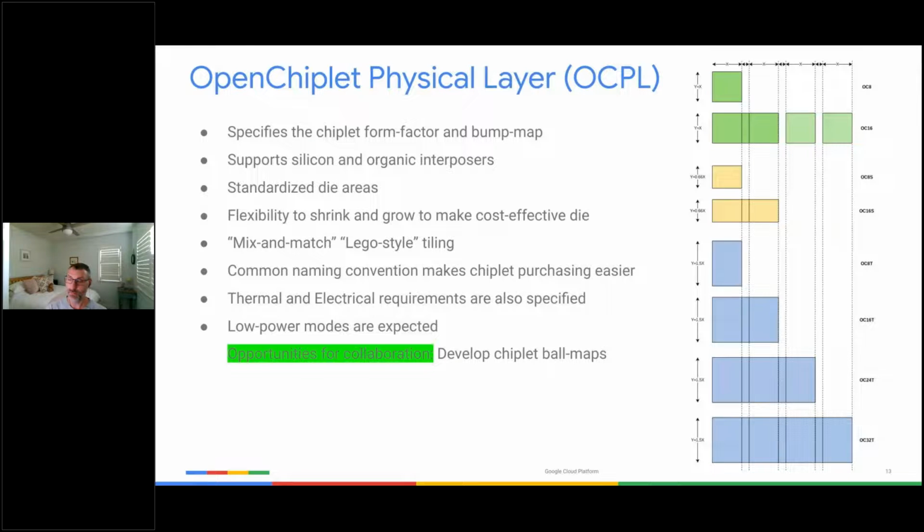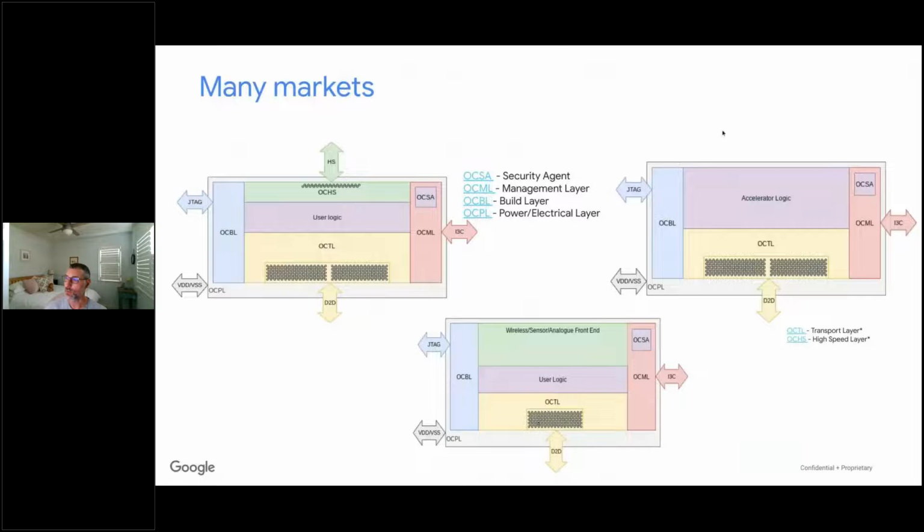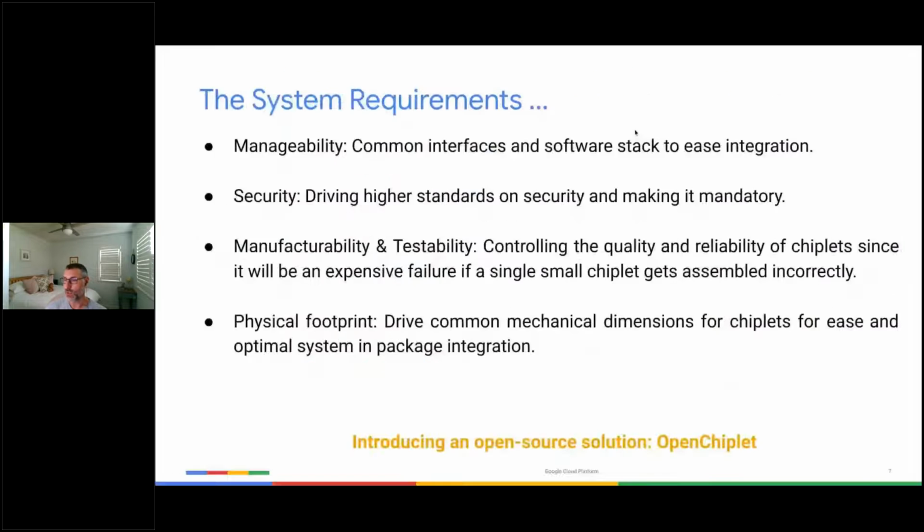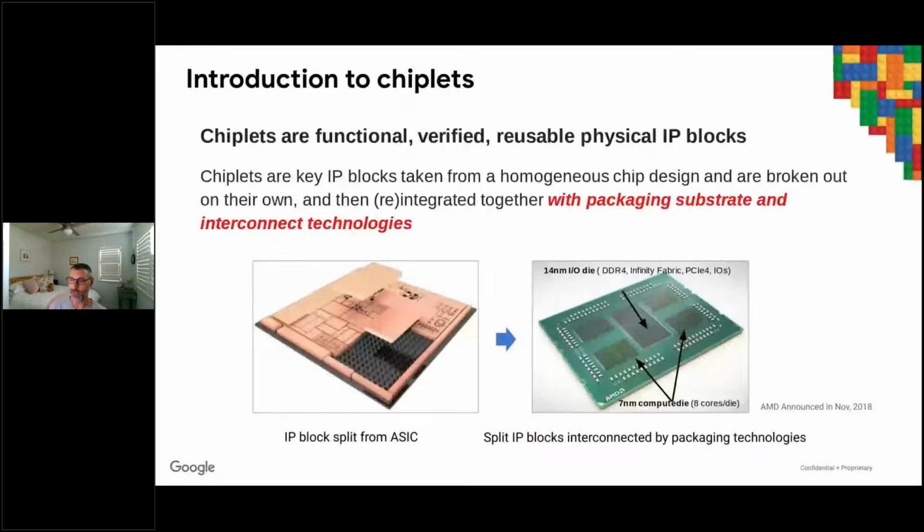Yeah, because if you went to a picture that looked like this orange thing, you're tessellating and tiling dies all over the place. It's an awfully complicated thing to assemble in the first place, just matching all of those design rules and thermal expansion, everything to do with assembling such a mismatch of die shapes and sizes could be awfully hard work in that particular case.